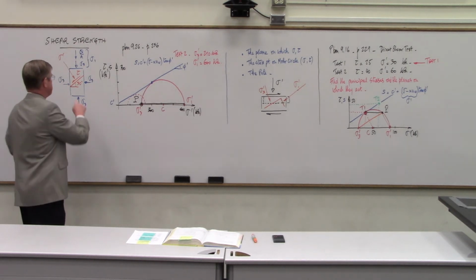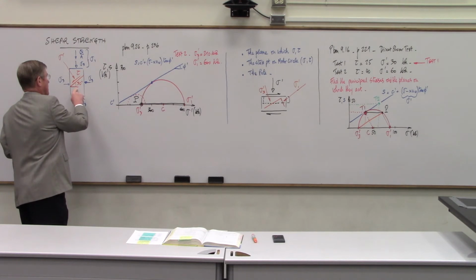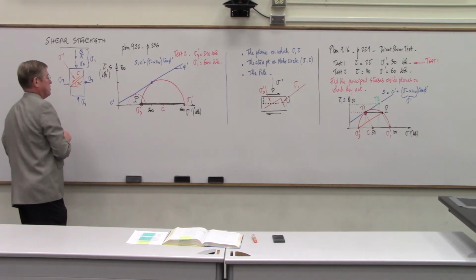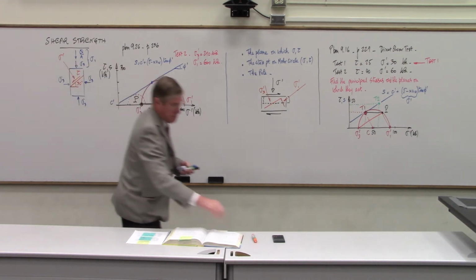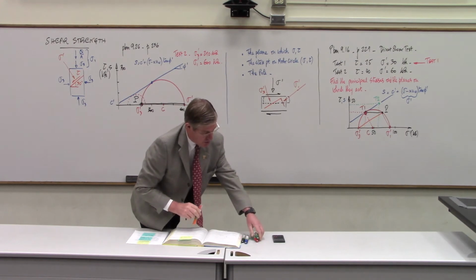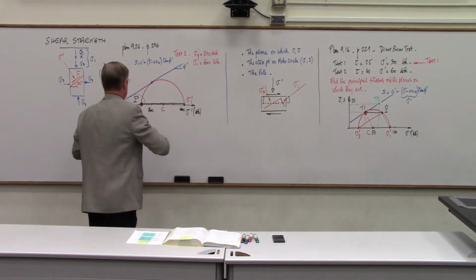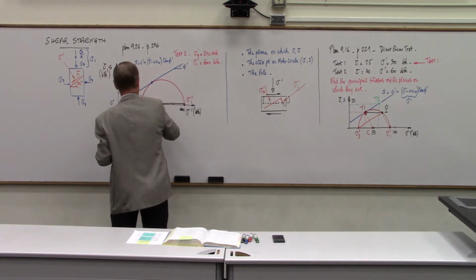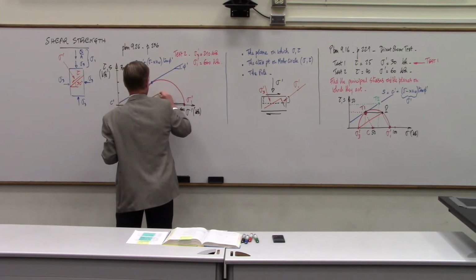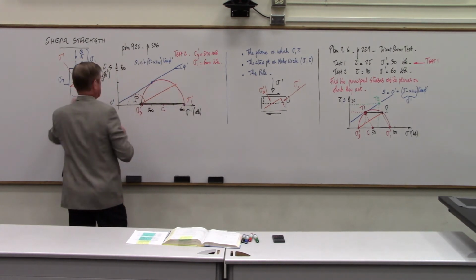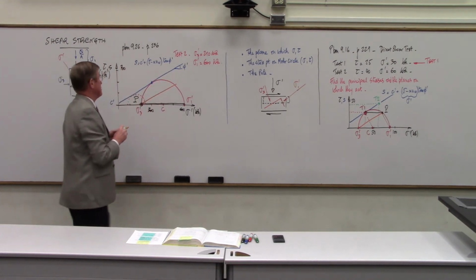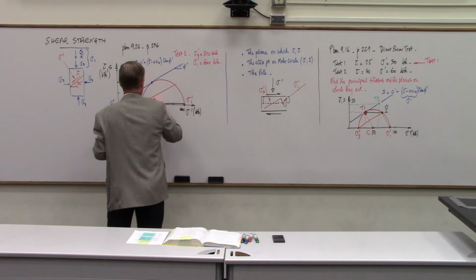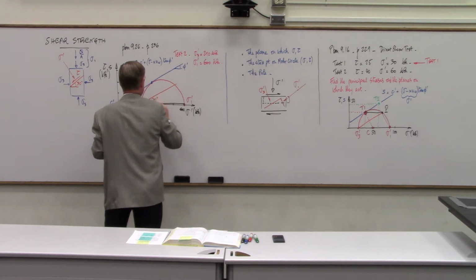The plane that we're interested in is the plane that makes a 30-degree angle with the horizontal. So through the pole, which I just found, I can draw a line that is at a 30-degree angle. That line is not parallel to the blue line, it just so happens that it looks like it is, but it's not, okay?